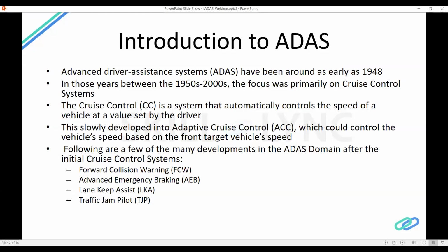So in such a case, like I mentioned, if suddenly the distance is lesser between your obstacle and your target vehicle, then this warning comes up. It pops up on your HMI interface. HMI here refers to human machine interface. All right, so this actually is a separate domain as such, all HMI controls, etc. It works very much integrated with ADAS, because anything we do in ADAS is about informing the driver, because as the name mentioned, it's a driver assistance system. So HMI is what assists the driver. So in this forward collision warning, a warning comes up to the driver saying you will be colliding, so you better override now, take control, or be prepared for an imminent collision. So that is what forward collision warning does.